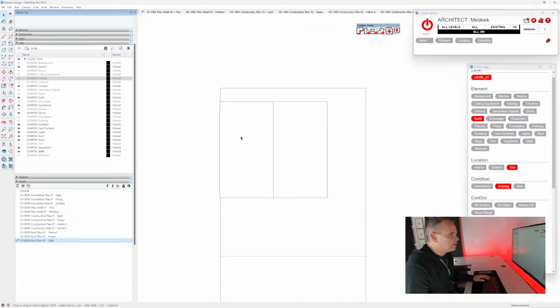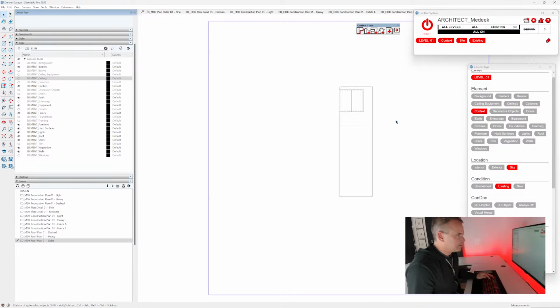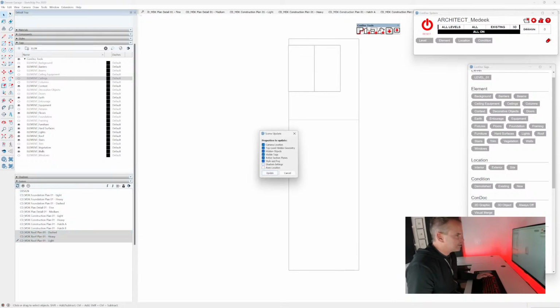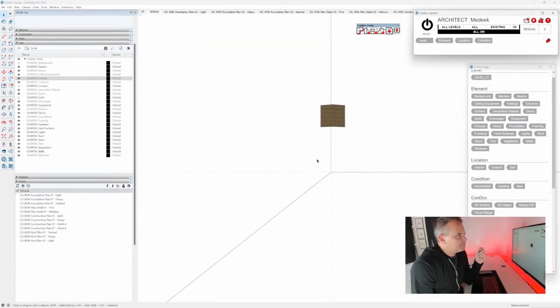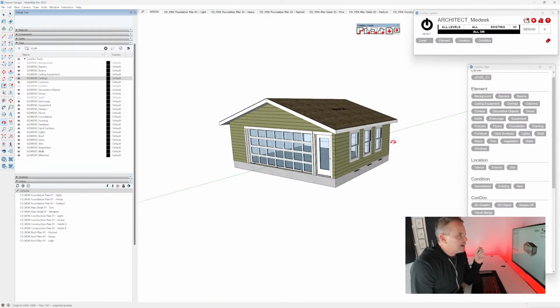When we look at this scene, we would want to see this, because this is gonna be our site plan. All right, and like I said, you could zoom extend some of this stuff, zoom out like that, and you can update this scene so that it's gonna show a little clearer the camera location. But the other ones are in pretty good shape. So I'll click reset twice, and that gets me a zoom extents. And now what we can do is set up some elevations.